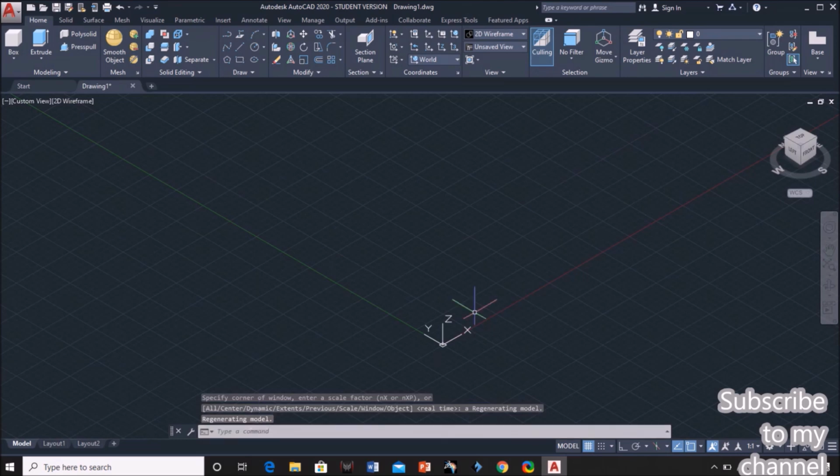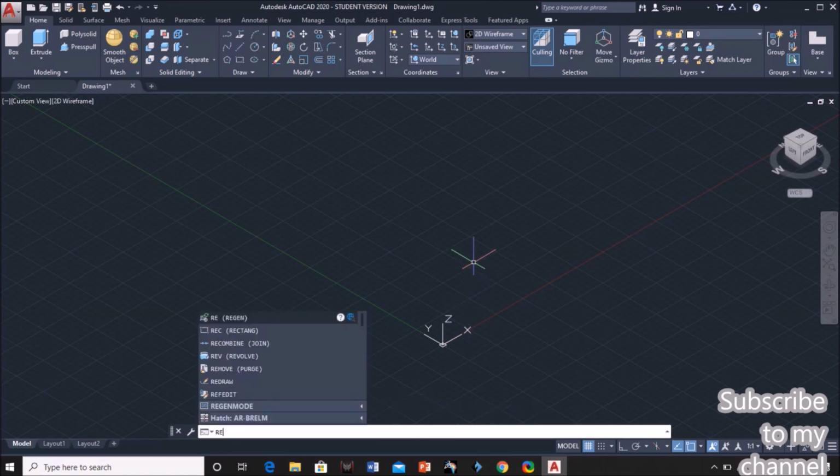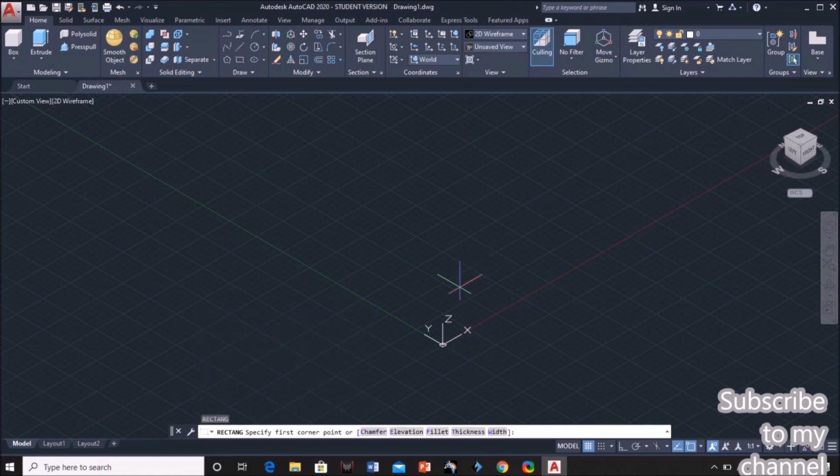Now I am going to draw a 2D object and convert it to 3D. I am giving the command as rectangle, REC enter. Now we need to set the first corner. Next, specify the other corner. Before specifying the other corner, I want to give the dimensions for the rectangle. So go to dimensions, D enter, and give the length as 50 and width as 50. Again it is asking for the other corner point.